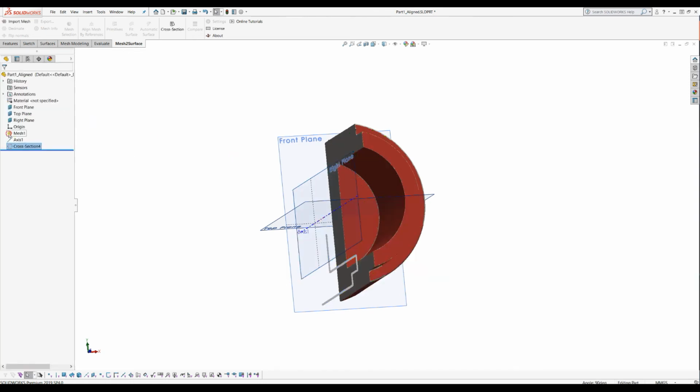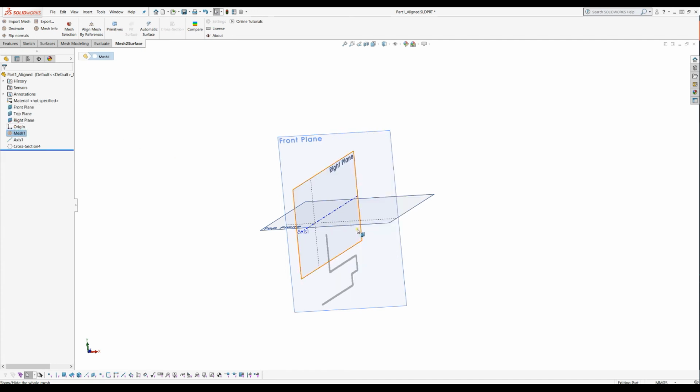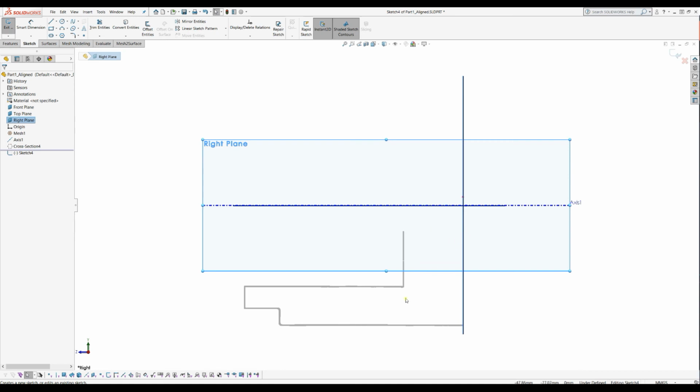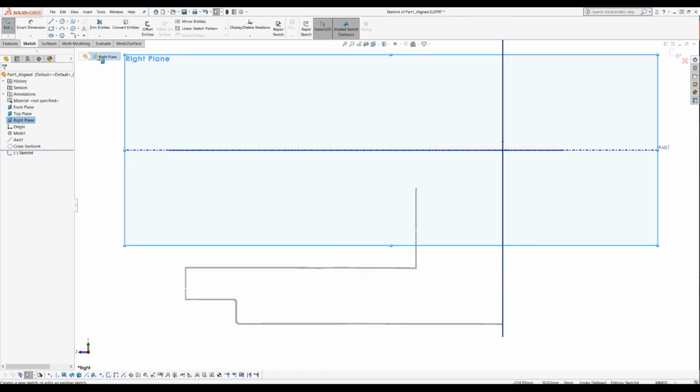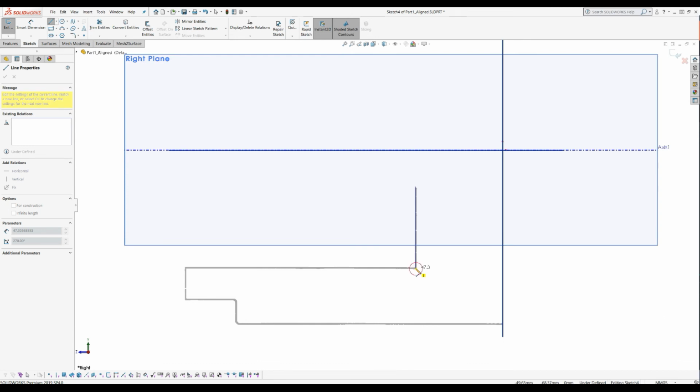And now let's explore again a little bit how we can use this. I'll hide the mesh because I don't need it. I will just take this and create my standard SOLIDWORKS sketch. As you can see now, I have a nice and good outline of my object, and I will just take my standard SOLIDWORKS tools. We'll just generate my profile here. I'm not so accurate, but you can do this in a more accurate way.